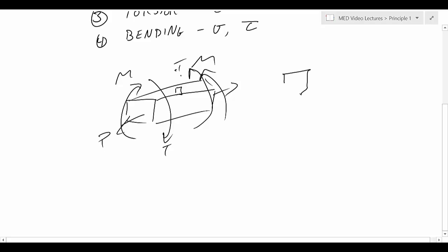That's our point, and we imagine it as some infinitesimally small block that has some loading. And we can say there is stress acting, let's use an XYZ coordinate system, on the X face acting in the X direction, normal to the X direction, we'll call sigma X. Sigma Y is the same, except acting on the Y face in the Y direction, equal and opposite, since we're starting with a statics assumption here that the elements of this part aren't moving around inside of it. We will have the same in the negative X face, the negative X direction.